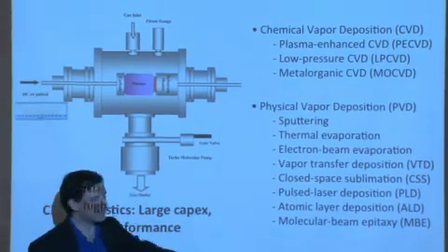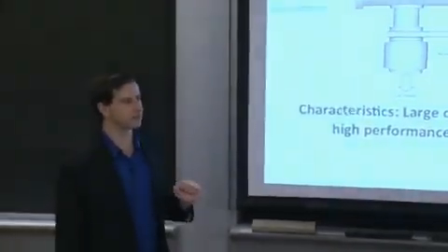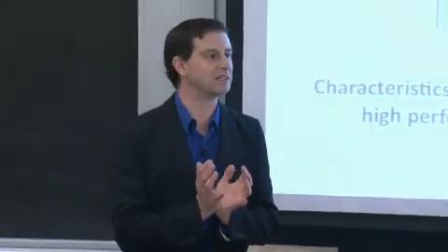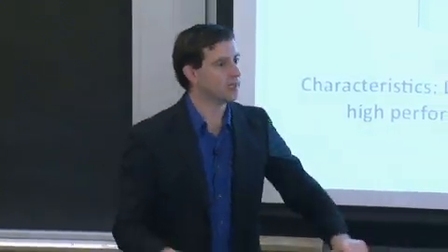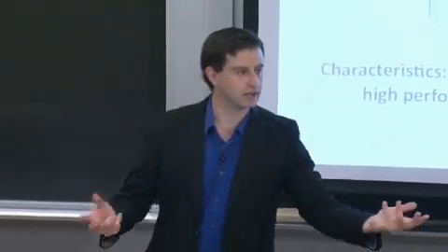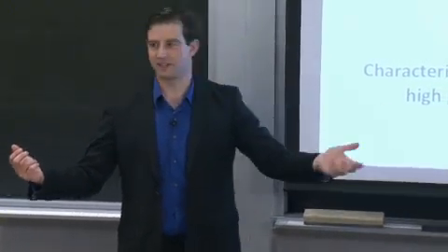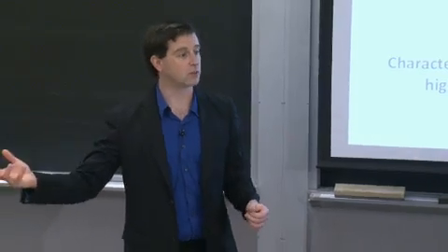And so a very simple way to think about the vacuum-based deposition technologies is a compromise. It is an oversimplification indeed, but it's an easy way to get started thinking of the parameter space of all these techniques. It's a compromise between speed and quality. Some of the techniques that are fastest also tend to be the lowest quality materials, and the ones that tend to be the slowest tend to produce the highest quality materials.